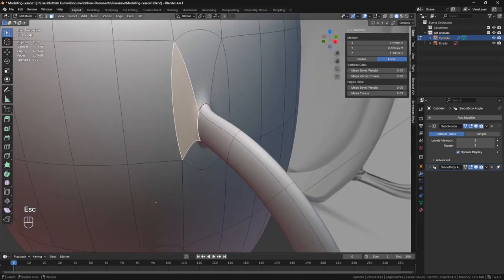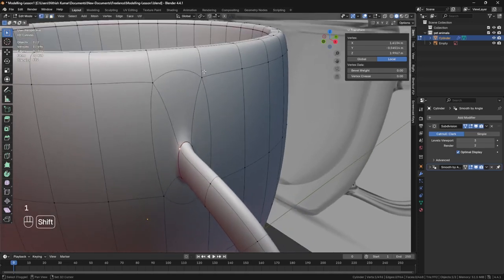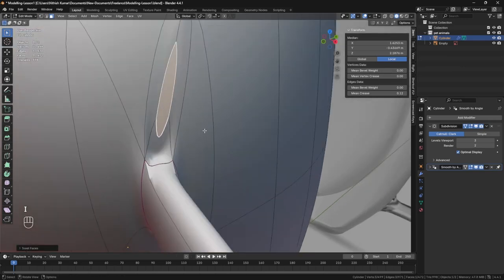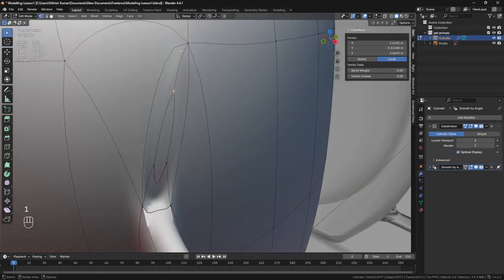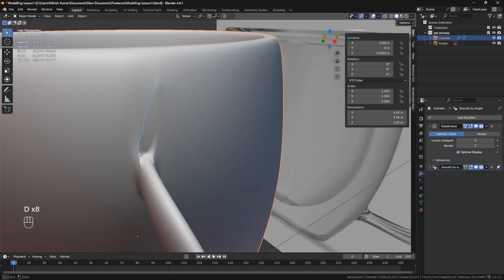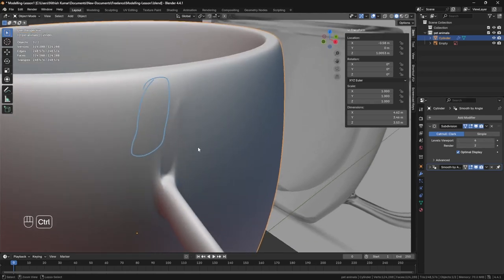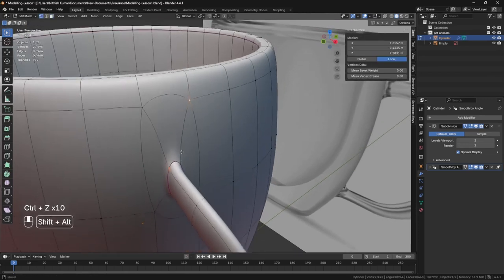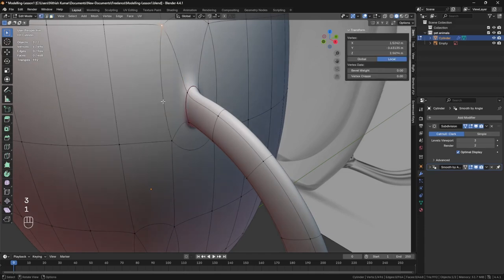Let's say if we didn't have this proper four facing, we have another, let's say, triangle. I'll just press J for join. If I press I, it will have just a different shape. So you can see it's not proper, right? And if you also increase the modeling thing, it will become much more awkward. So it's always best for 3D modeling practices to have a proper four facing or four vertex.